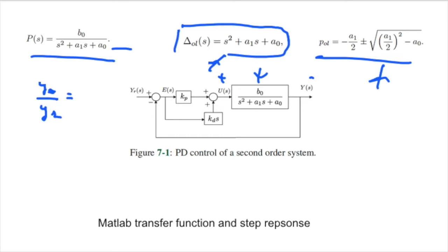If the poles are in the left half of the S plane, like something like this or this, then it's a stable system, right? The open loop system is stable, otherwise it is not. If anything goes in this area, we are toast. But after we apply the feedback control, we can drag those poles and bring them back to the left side, right?